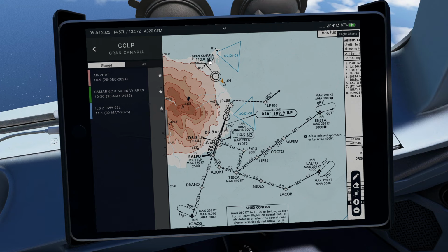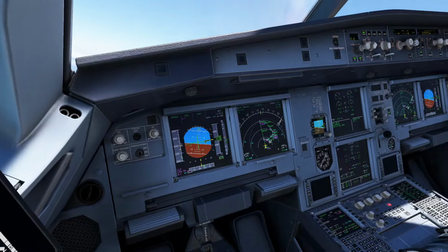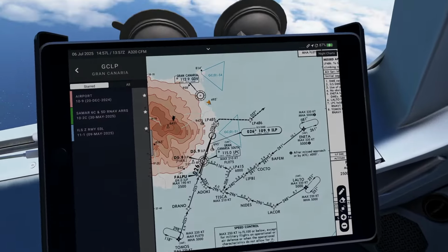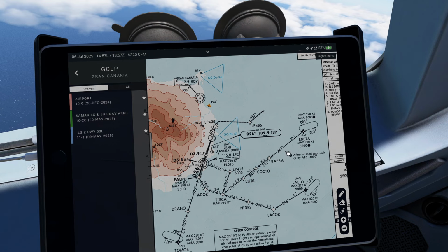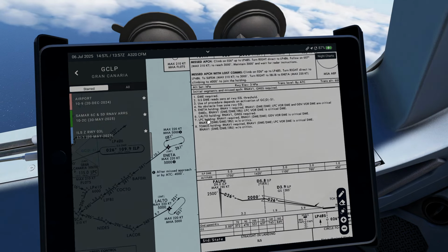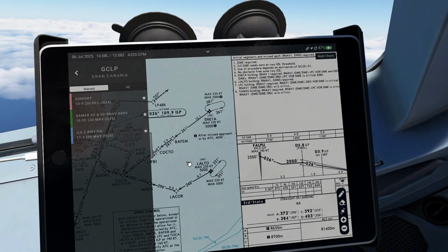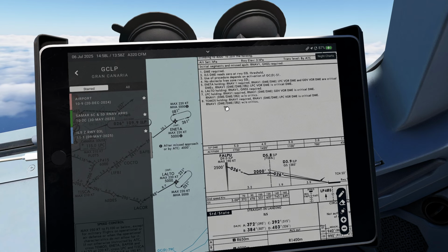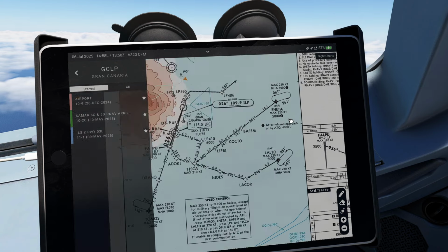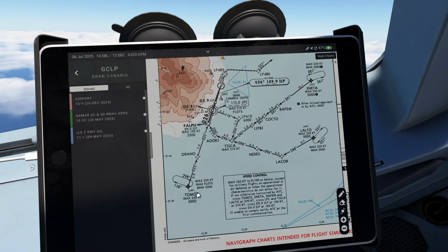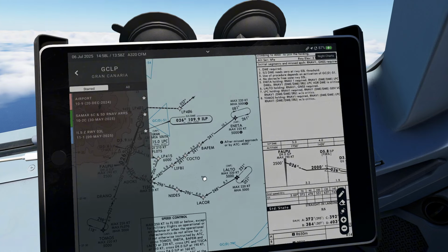Also we have two VORs, Golf Delta VOR just passing right now at or above 7,000 feet. As you see, we are at 9,200 feet, and the other VOR is here, Lima Papa Charlie. But the other item, for LAL2 holding RNAV1 GNSS required, is that we are descending toward LAL2, and Lima Papa Charlie holding, which is not our case actually, and TOMOS holding, which is located at the south, actually east, southwest of the airport, which is not our case totally.